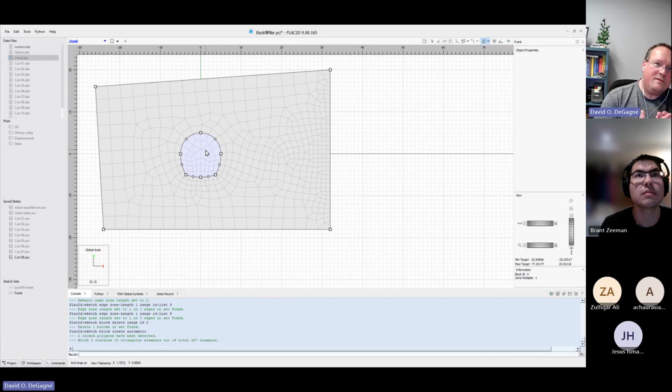Okay, so have you ever seen a 2D analysis where in 3D, if you've got a tunnel and you're excavating along a drift or a tunnel, you can put a measurement point in at some point and then continue to mine. If you're monitoring the vertical displacement at that point, what you'll see is this gradual closure, the tunnel roof will start to close further away from the face of the tunnel. And so it's sort of like that.